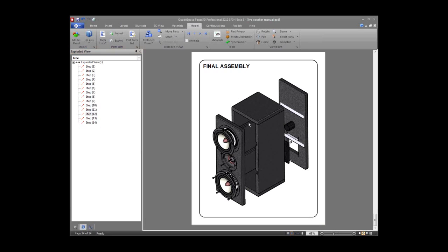Say you updated this woofer in there, then this woofer would be replaced with the updated component in the same position, and it would be replaced in all the graphics. These are keyed on by part name. So if you wanted to do it automatically, then it needs to have the same part name between Rev A and Rev B. But that's really what it's keyed on. If not, then you might have to make some adjustments, or if there are new parts, then you'll probably have to make some adjustments too.